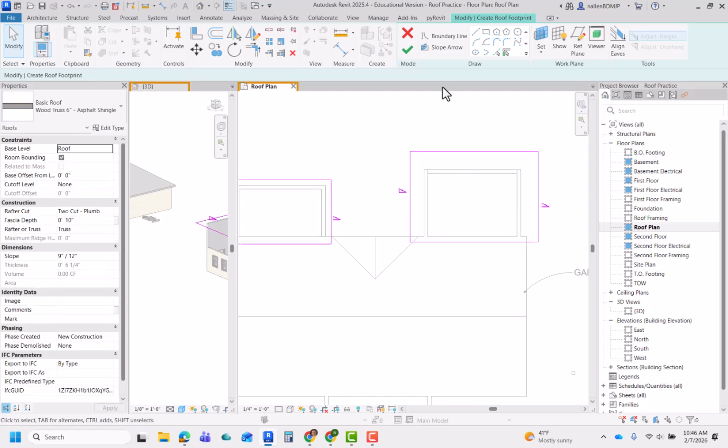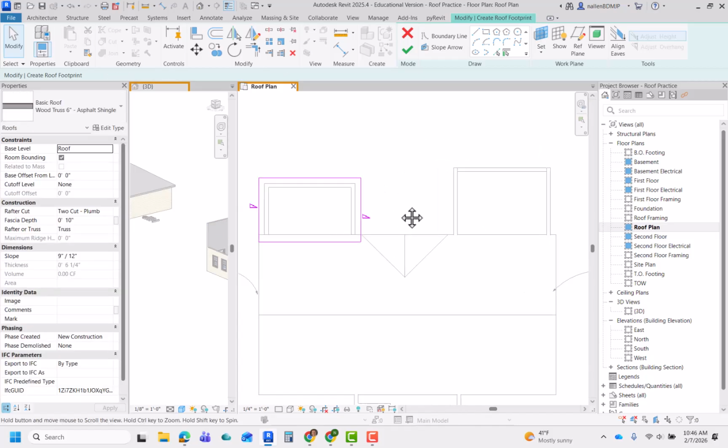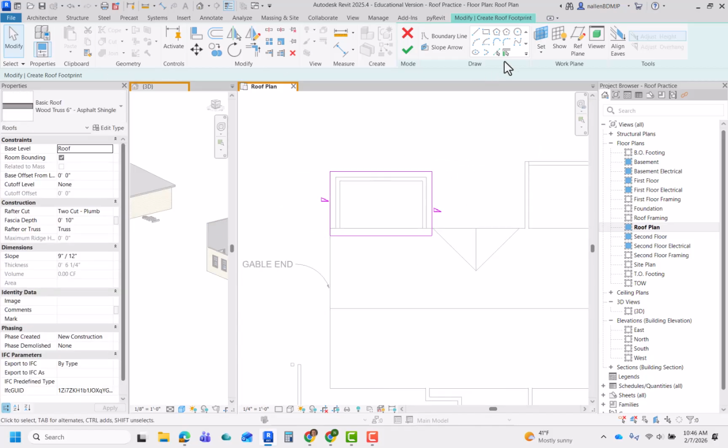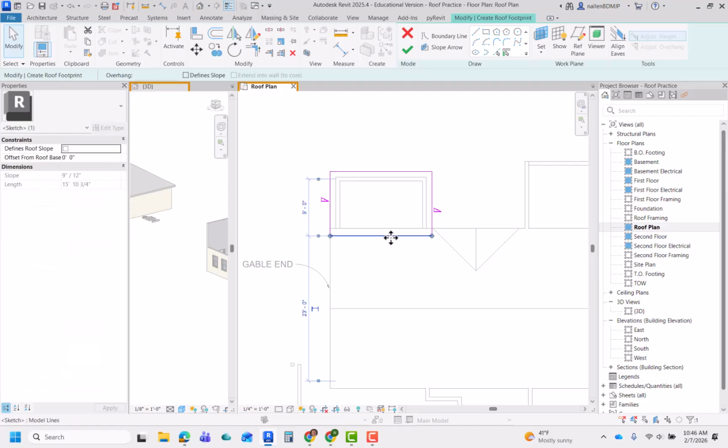And that's because using the lines doesn't actually attach this to the walls. So it actually positions it differently. It makes your overhangs different. It's just not really a good solution unless you really know what you're doing. I would always do it the way we did over here. Use the pick walls tool as often as possible, and then just use lines when you have to close something up. Okay.